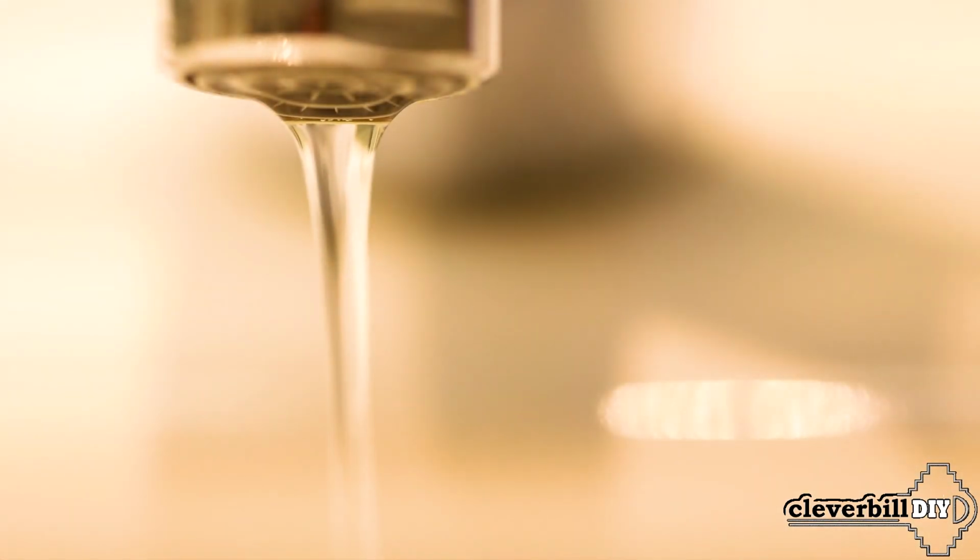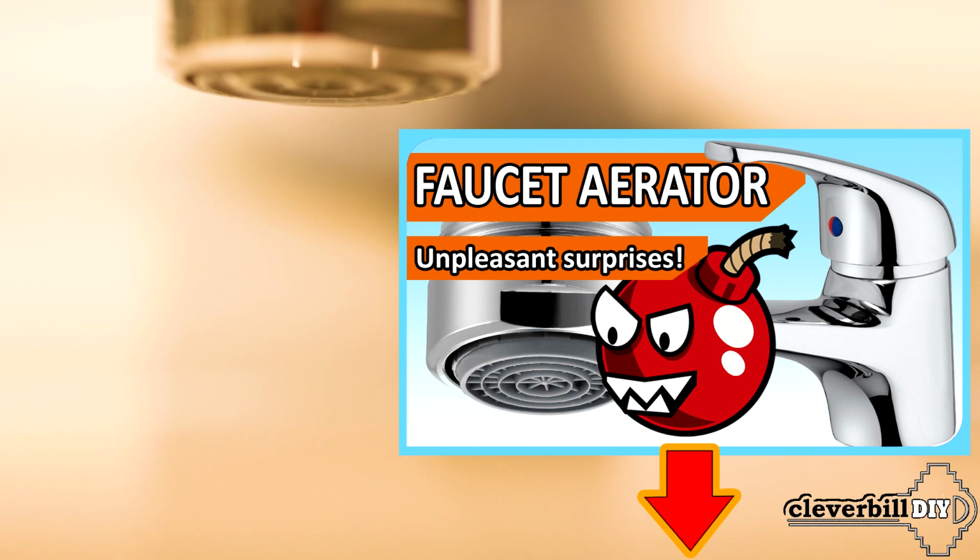Mixer aerator, or the so-called mesh, located at the tip of the mixer spout. Large particles entering the aerator can clog the aerator mesh in the shortest possible time. At the beginning of the blockage, water from the mixer will flow in a thin stream, and then it will stop flowing completely. To make matters worse, the hot water can begin to push out the cold water and end up in the cold water supply. You can find out more about squeezing out cold water in my other material, the link to which will be in the description of this video.